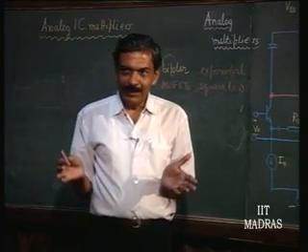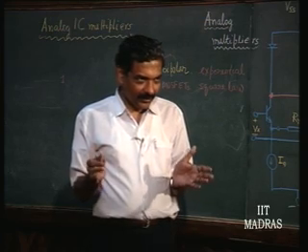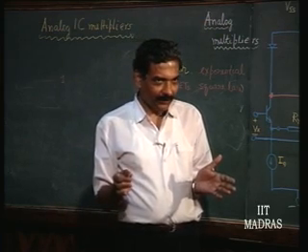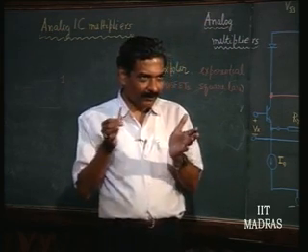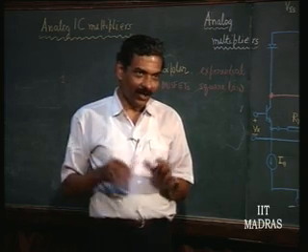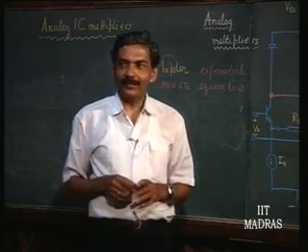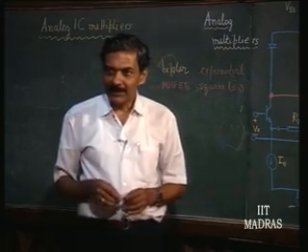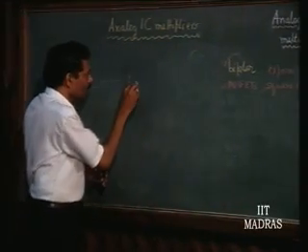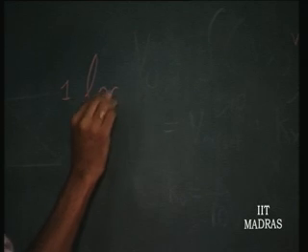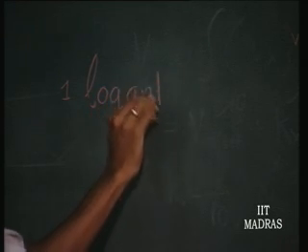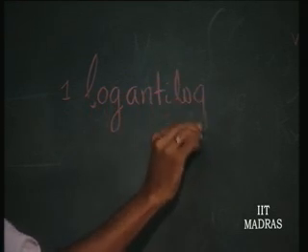This is now going to be the multiplication operation of Vx Vy by Vref. Log of that is what you have got. You have to now take antilog, and you will get the multiplication. So, this multiplier is called log antilog multiplier.